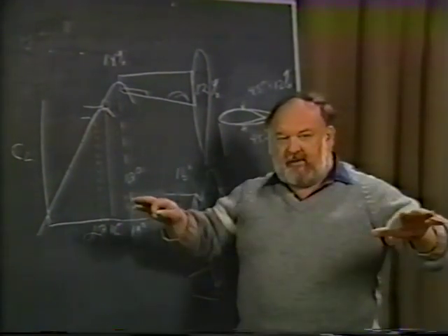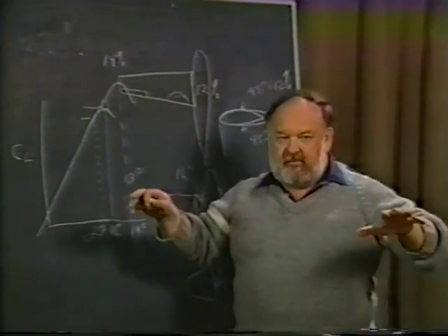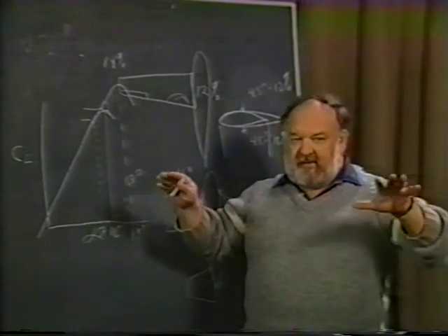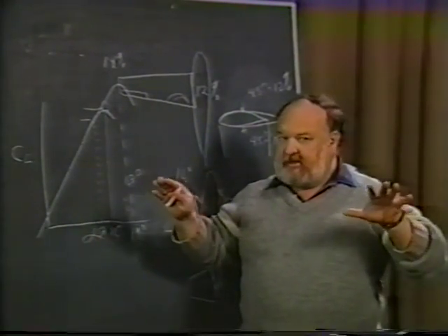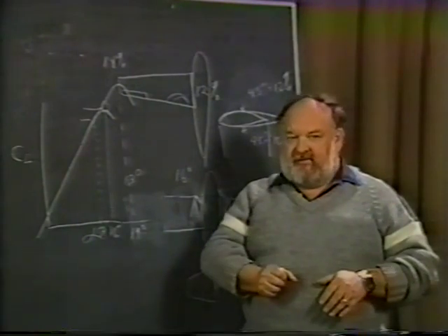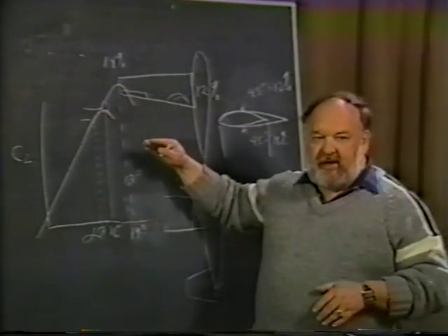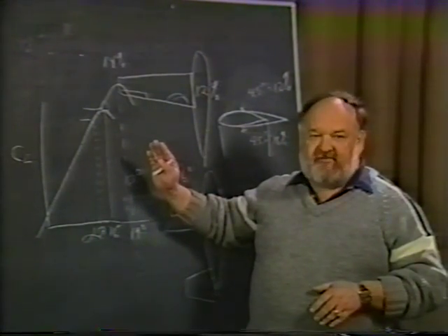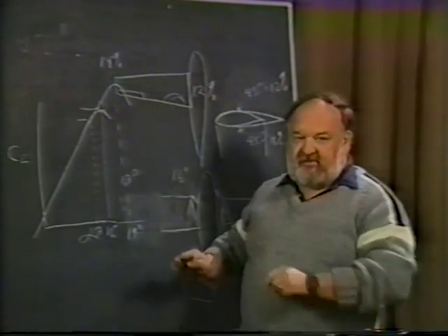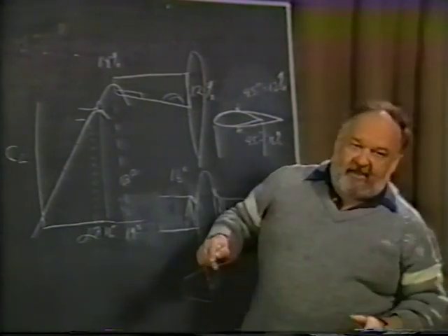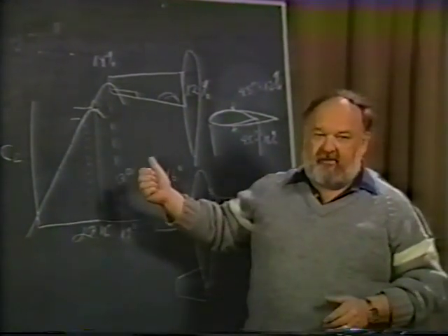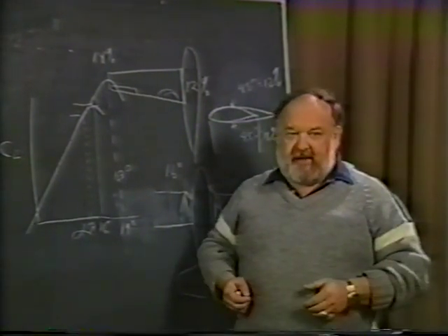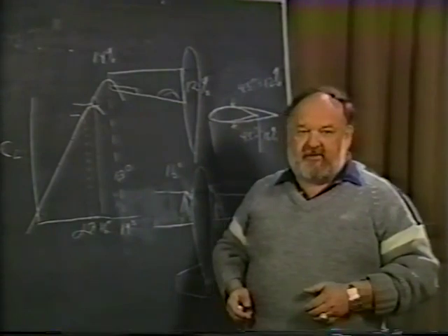Here you are with the straight wing, straight sections, the old USA 35M airfoil on it, and it'd be real fine, except if you were near a stall, you still hadn't stalled yet, the airplane's flying, and then you go ahead and move the stick to the left, and the right aileron comes down. As it comes down, it tries to produce more lift out of that wing than it's capable, and that section stalls. Now what did happen? You wanted to bank to the left, so you gave left stick, but now the right wing stalls and the airplane goes the opposite direction. Immediately it confuses the pilot, and off you go, possibly into a spin.